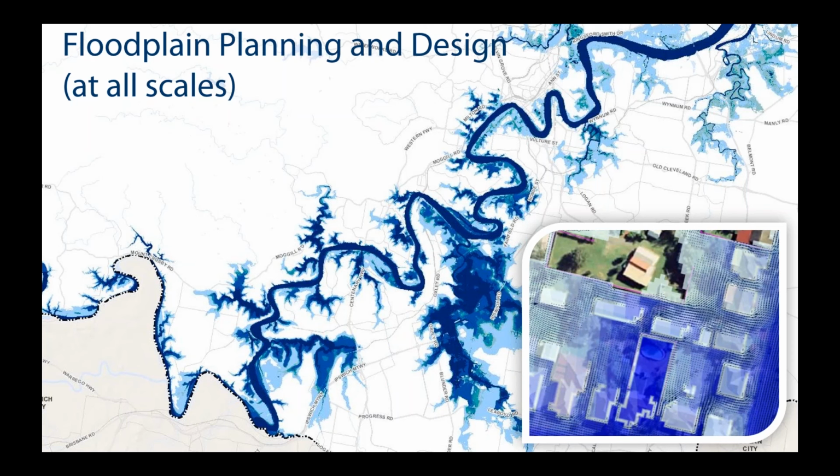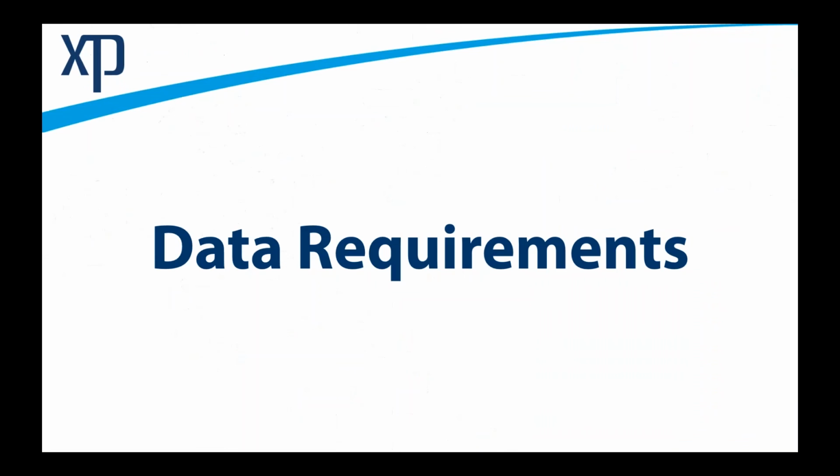Okay, so data requirements. So we now know the history. Had a general discussion about the applications. What does it take to make a 2D model? Typically we start with our surface data. And this can come from a variety of sources. Normally you'll start with your aerial LiDAR data, so it's aeroplane survey data. And then you'll supplement that data set with, say, bathymetry or land survey.